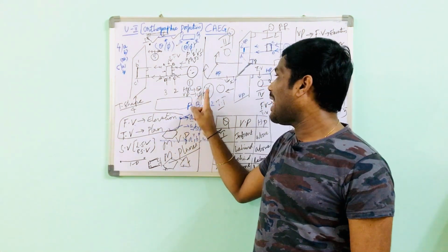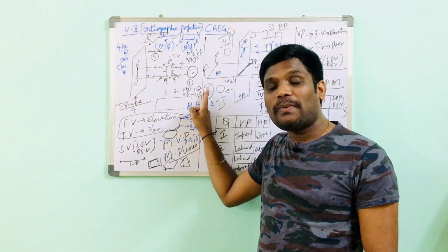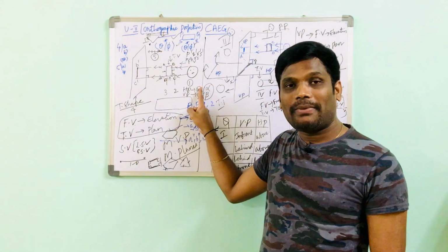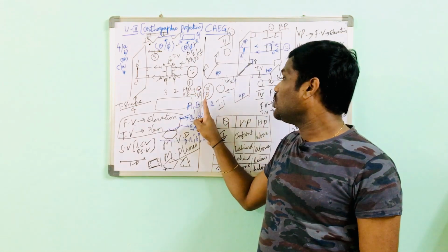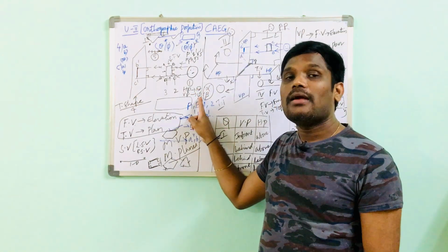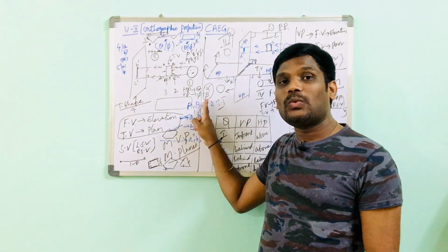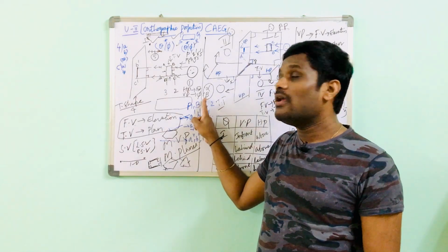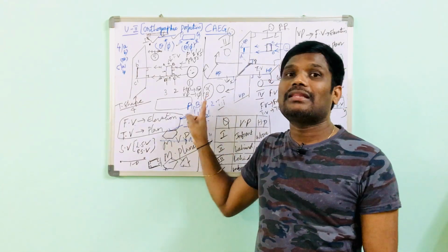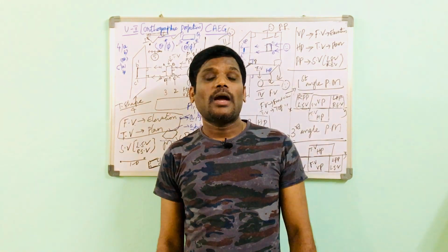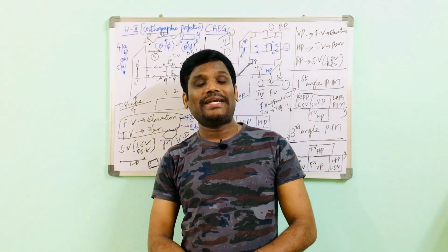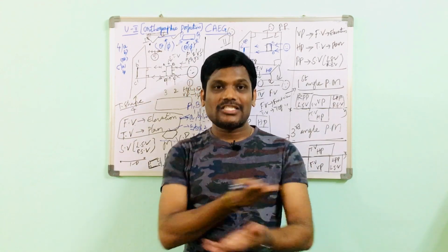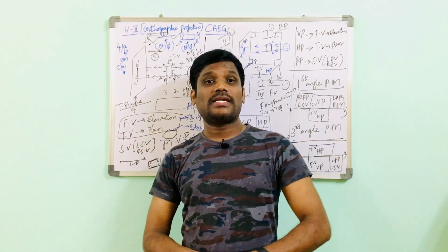So the apparent angle alpha represents the inclination to the horizontal plane, which is greater than theta, and the inclination to VP is represented with phi. But the apparent angle with respect to inclination to both HP and VP, the greater angle, is nothing but beta. Problems on lines inclined to both the planes are also there on my channel. Please go through them and refer, dear students. And the XY line is nothing but the reference line.